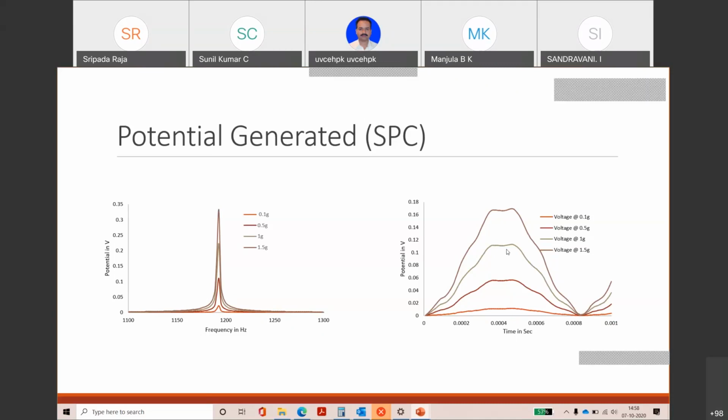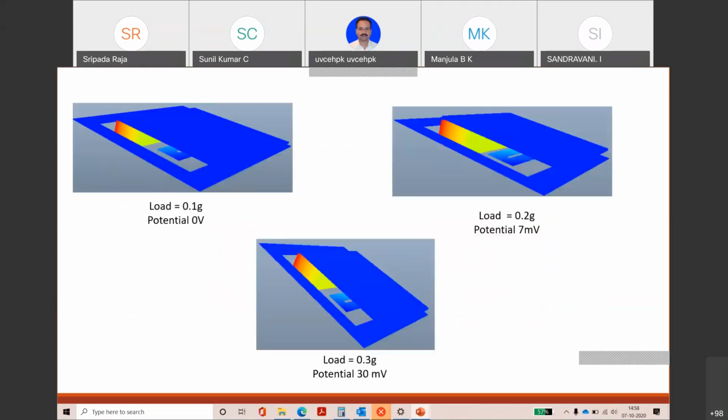resonance. So each one of the plates has piezoelectric material put on it. So one plate captures the vibration in the range of 1 kilohertz, another plate captures the vibrations which are less than 100 hertz, and both of them contribute to producing the charge. Okay, so here these are some of the videos, and I think the displacements are quite small here.